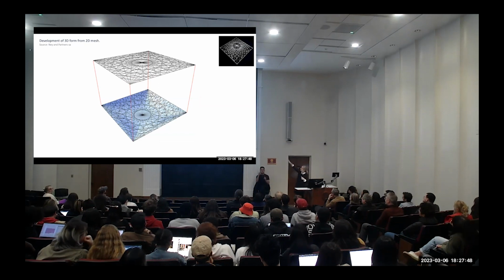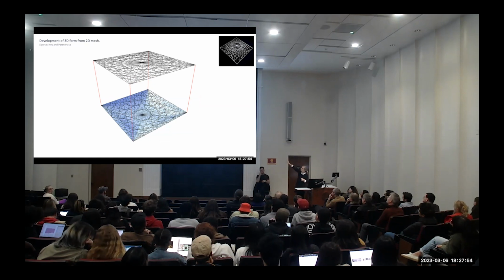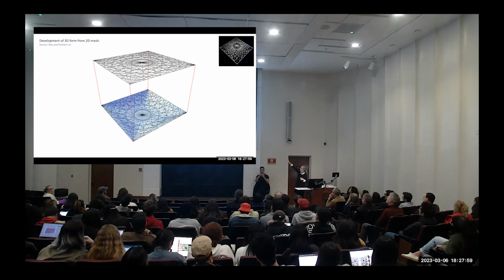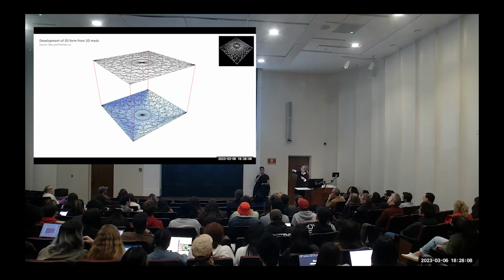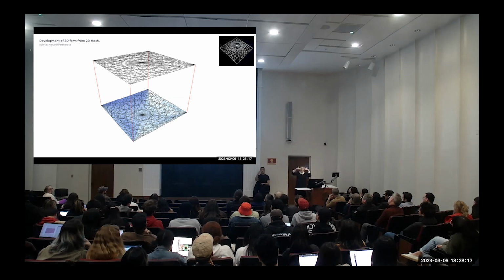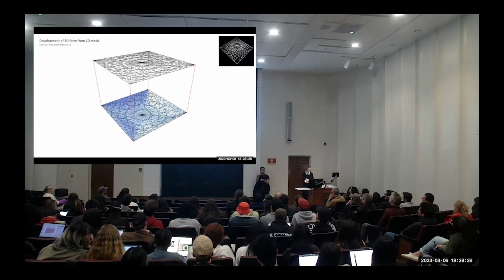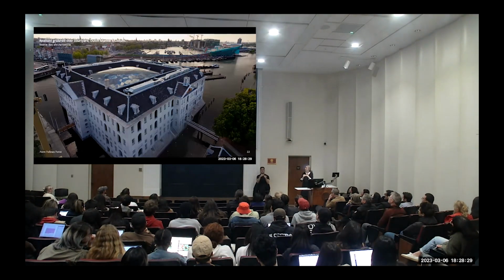And so what you see on top is again the same geometry extracted. And then I was very lucky, I just finished my PhD. We used algorithms that I developed during my PhD to model this planar structure as a spring system, like a network of springs. So if you imagine every line to be a spring, and at the node intersections we put a load which represents the self-weight, and then we get this kind of hanging chain model, like a hammock. It was Robert Hooke who said that if you have a hanging chain, or a hanging chain network, and you invert it, you end up with a perfect cupola. And so, because we used this technique, all the members in that system could be designed very, very thin.